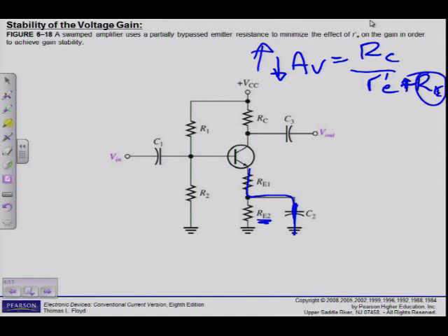Okay, so what am I doing? Remember, R'e unstable, very small resistance, but with a big resistor, no problem. Voltage gain is stable, but that big resistor is too big. I want to increase my voltage gain, so I'm splitting the value of RE into two. So I have now RE1 also in my formula there, which is now only 500 ohms and not 1000 ohms anymore, and I get a bit more voltage gain. Now I've got a stable circuit and I have increased my voltage gain a bit. Alright, that is why we do swamping.